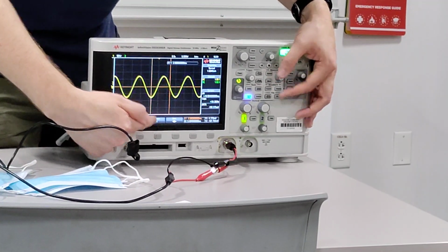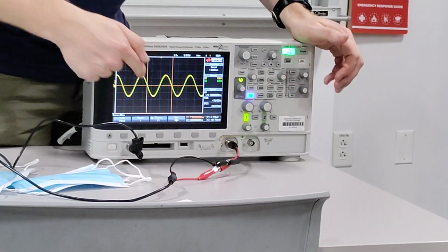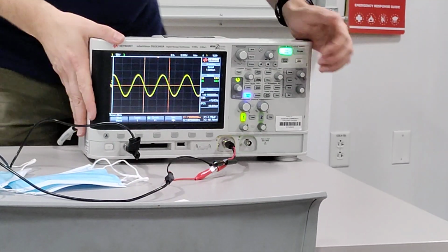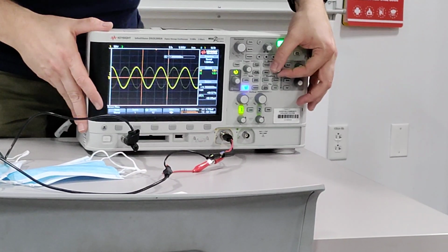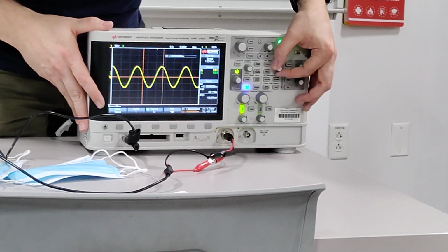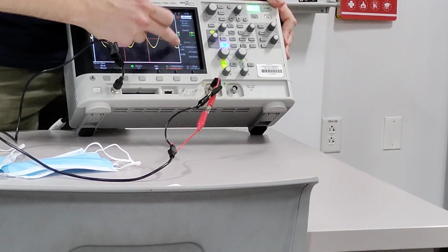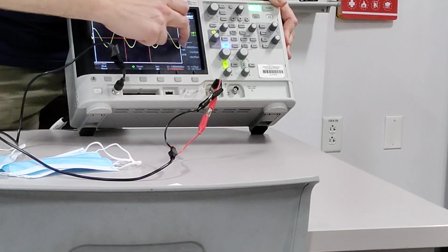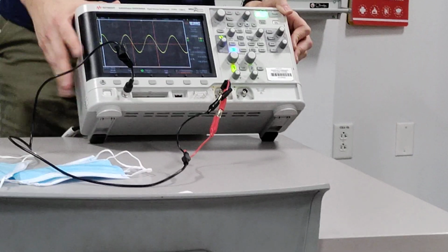And I am then going to turn this knob, and there's a vertical line you can see moving right here. So if I put that, say, right there where it starts dropping into a new signal, and then I change to x2, I can set the other one right there, and then I can tell myself pretty accurately that 14.1 milliseconds is the period of this signal, and it just gives me that on the side.